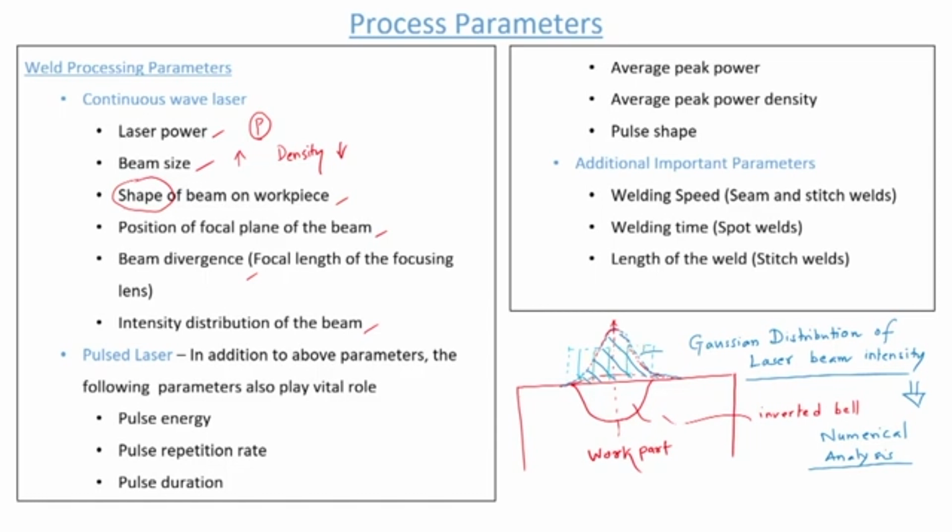So, this is the area of application, and the power is applied uniformly over this area, that we call uniform distribution. If the laser beam width is very small, in microns, then it is easy for computation to use the uniform distribution of heat application.